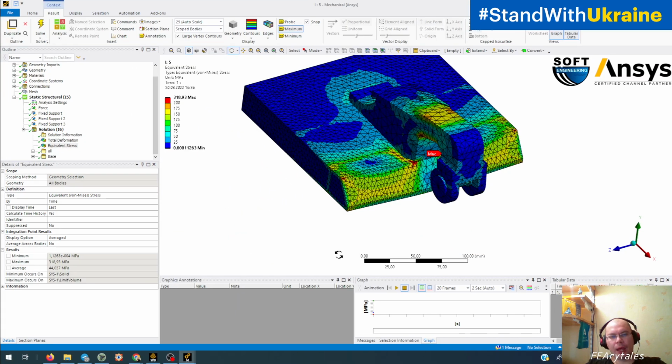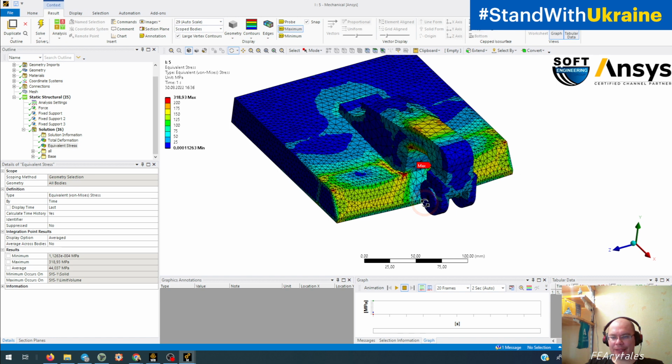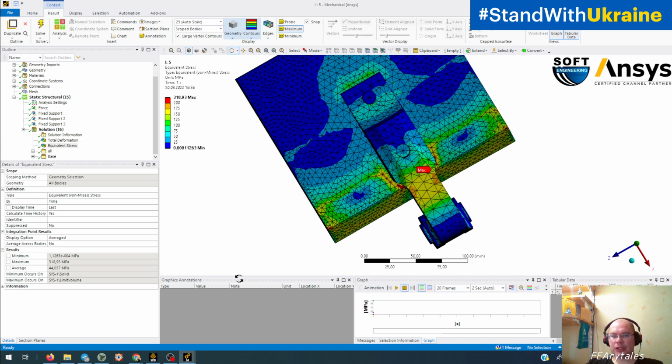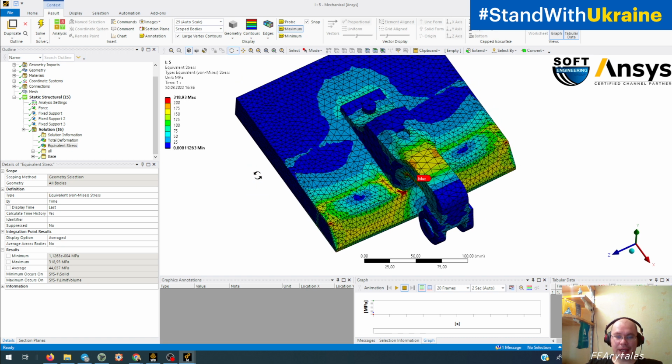And when you need to understand if your mesh is correct, if your mesh has adequate size, and so on, you need to check your stress distribution or total deformation distribution or distribution of the result that you want to use as a result in your design.